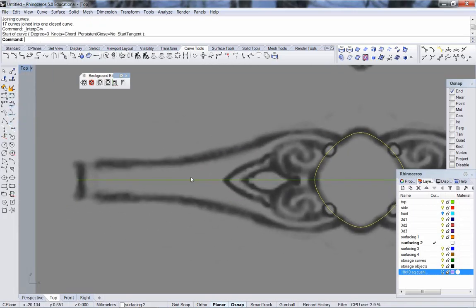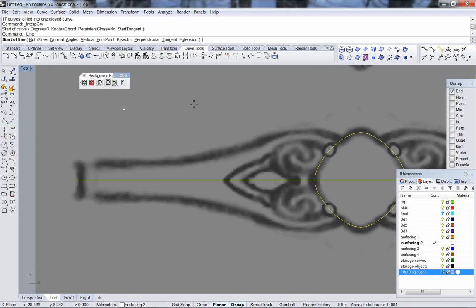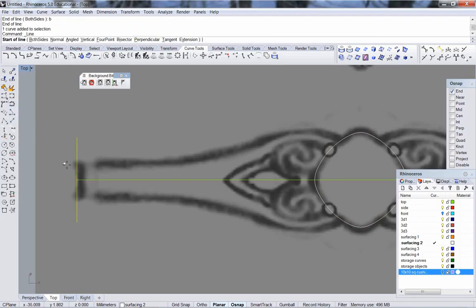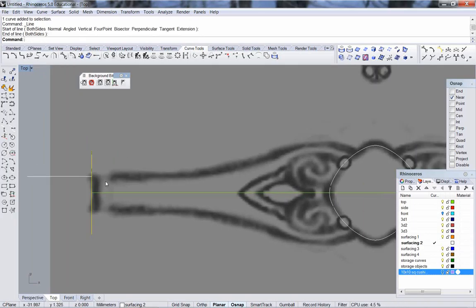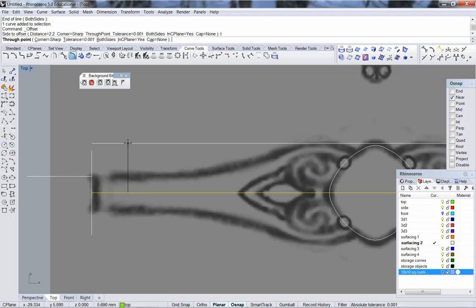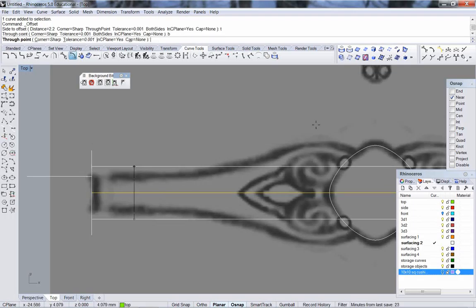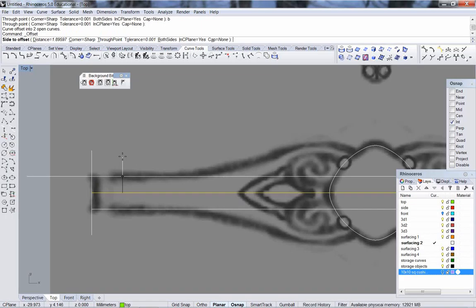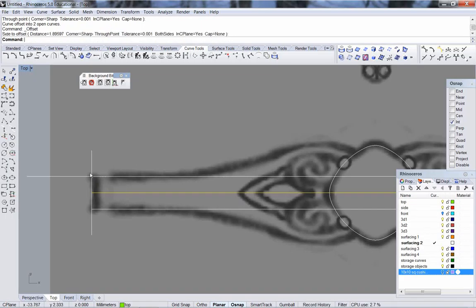I'm going to do a bit of a tricky thing here. I did this in class too as I was demonstrating. I'm going to draw an end line here, a barrier, and then I'm going to draw a straight line off of that using near snap, running away from my shank. Going to check and see what that thickness is. It's 1.89. Okay. All right.